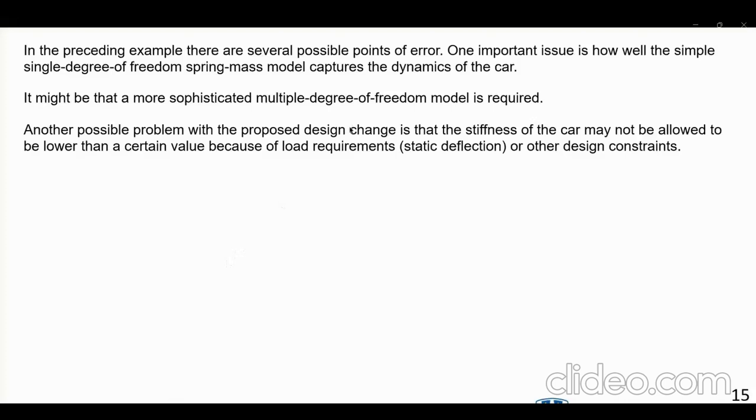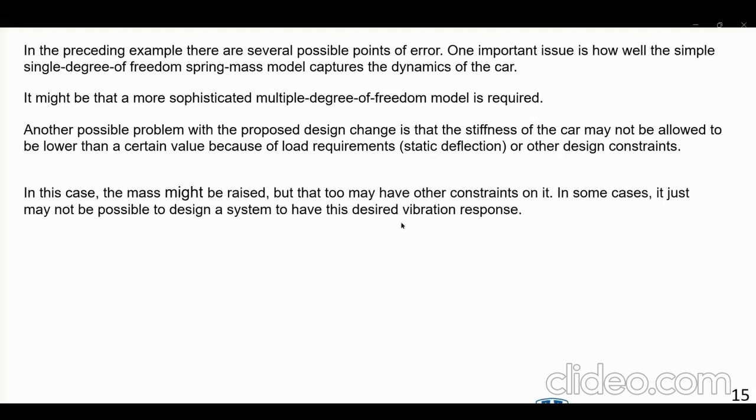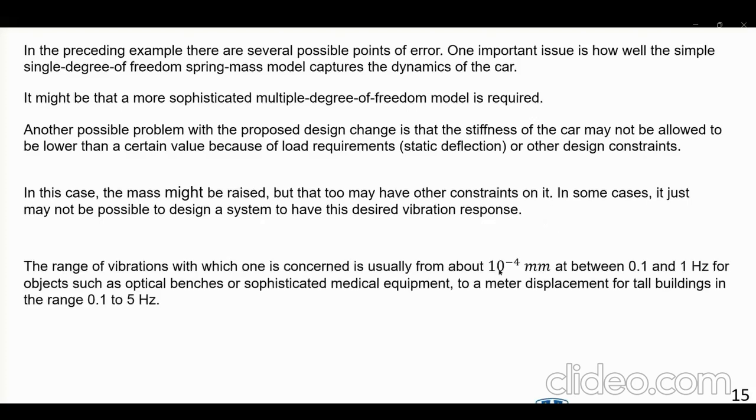And that was beneficial for the sensation of vibration by the passenger. But if you make it out of gum, okay, then obviously it can't support its own static deflection or the weight of the car. Or you may decide to increase the mass, but that may not be possible because more mass means more fuel, etc. So that may not be feasible.